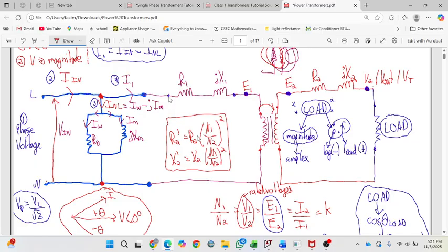So basically, the turns ratio will just flip depending on what side you're going from or to. Yeah, that's really it. Correct. And that will give you the equivalent impedance seen on the other side, because it wouldn't be the same.